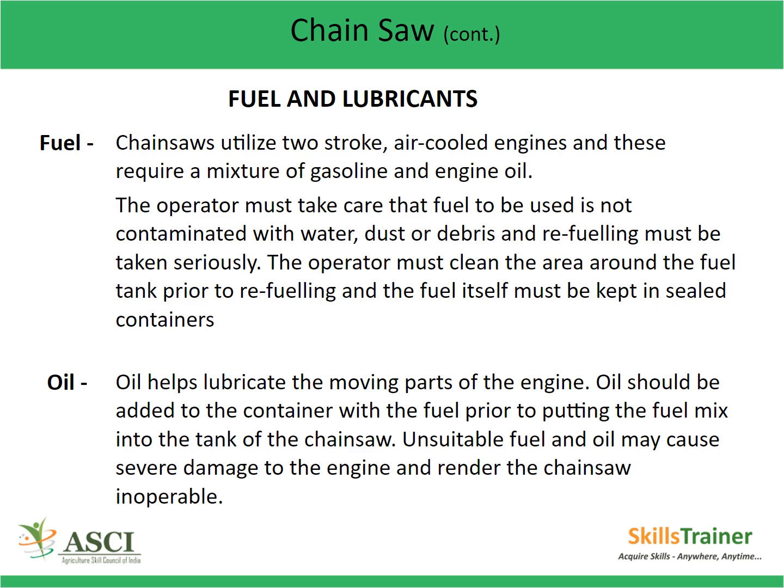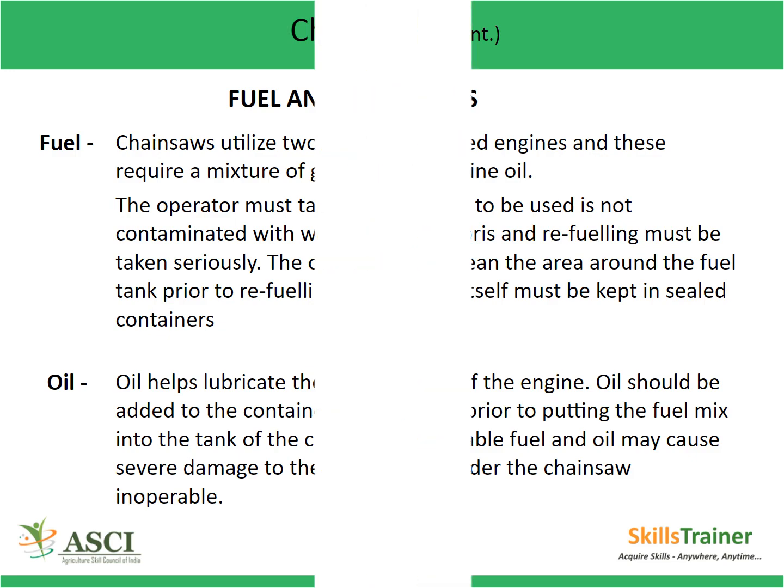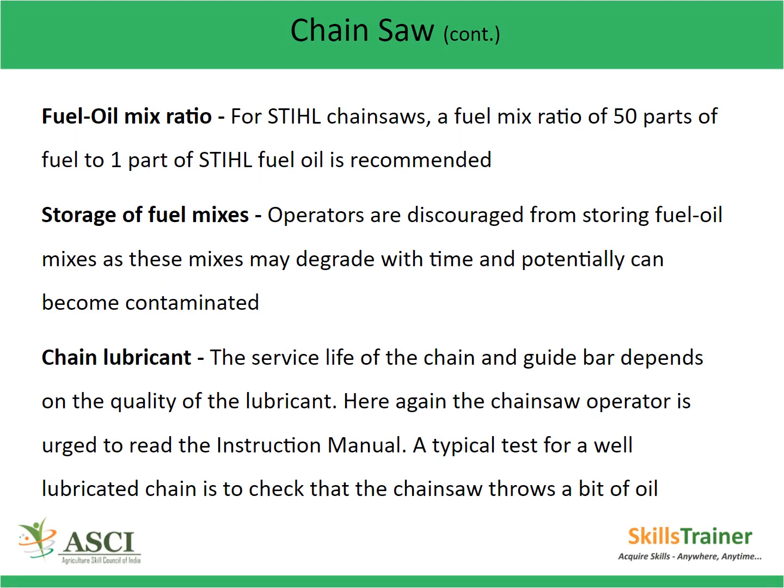Oil. Oil helps lubricate the moving parts of the engine. Oil should be added to the container with the fuel prior to putting the fuel mix into the tank of the chainsaw. Unsuitable fuel and oil may cause severe damage to the engine and render the chainsaw inoperable. Fuel oil mix ratio. For STIHL chainsaws, a fuel mix ratio of 50 parts of fuel to 1 part of STIHL oil is recommended.